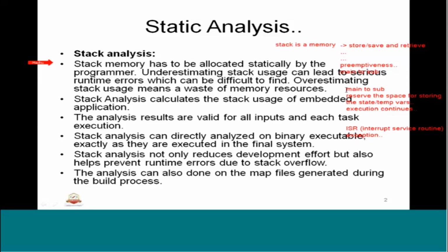Then once the ISR returns, that state will be retrieved back and the execution will continue. So for this there is a dedicated memory that is called stack. This stack has to be defined during linking.